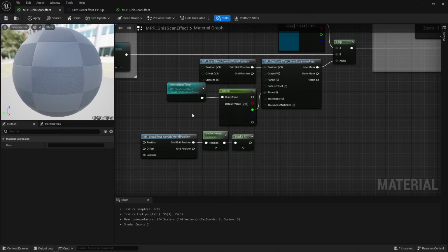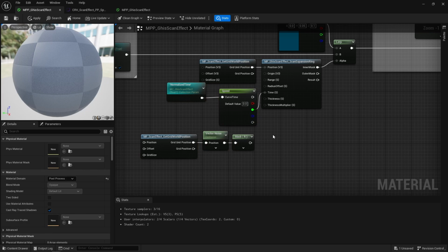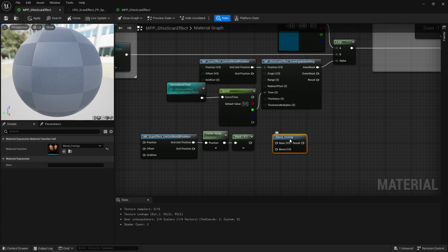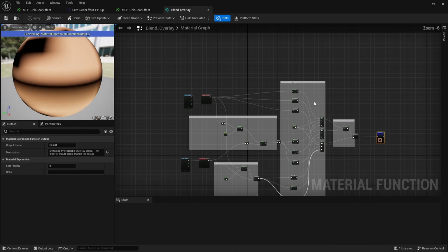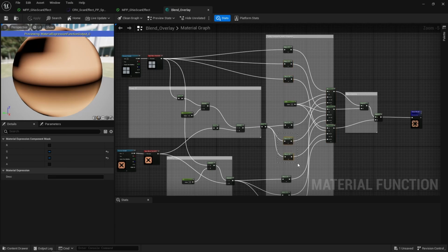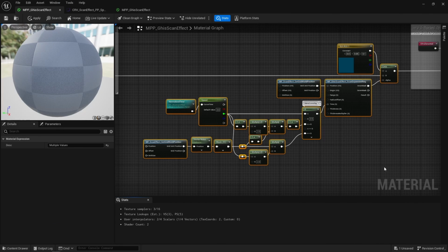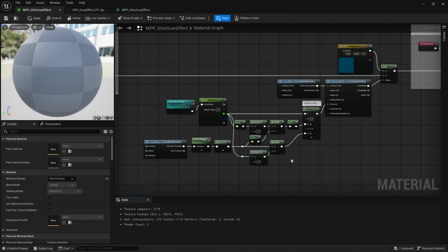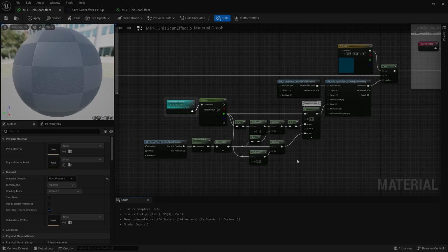And I'm going to blend that with a remap time using an overlay mode, kinda like layers in Photoshop, right? UE actually has a built-in function for this called blend overlay. It's meant to be used with an RGB vector though, so I just got rid of that green and blue channel logic to end up with that small node graph. And that's a blend overlay for just one channel. Why an overlay effect though? Well, I still want that time to be 0 when it's 0 and 1 when it's 1. I just want some noise when it's between 0 and 1, right? An overlay does precisely that.